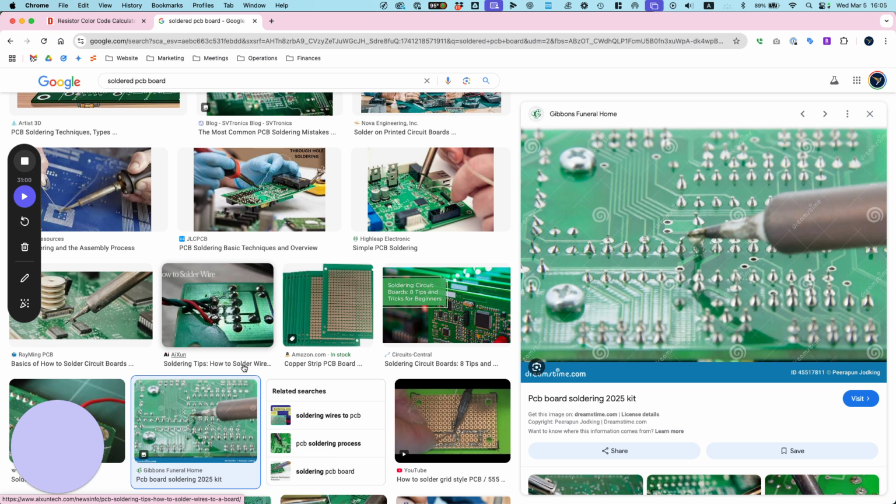So when you measure it, it's going to go up to like 4.2 volts, and when you use it, it's going to go down to, let's just say 3.2 for sake of simplicity. Really, you don't want to stop at 3.2. That's a little low. 3.3 is kind of my minimum.